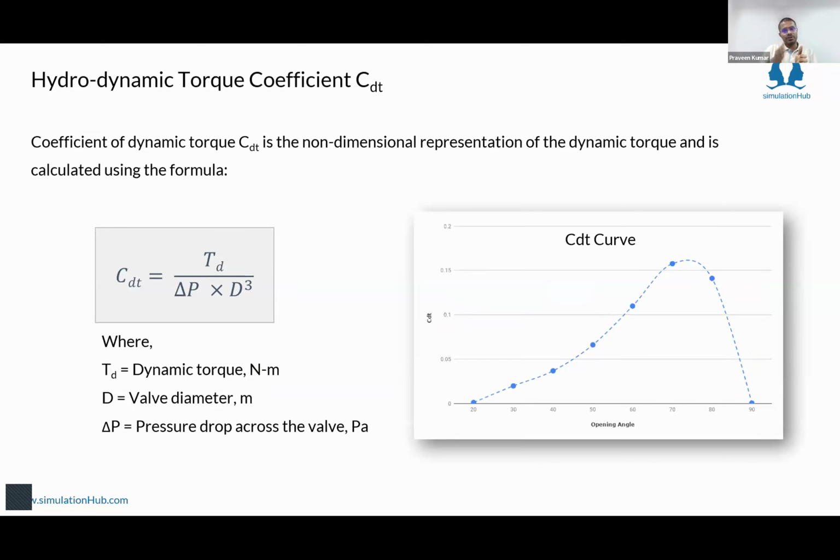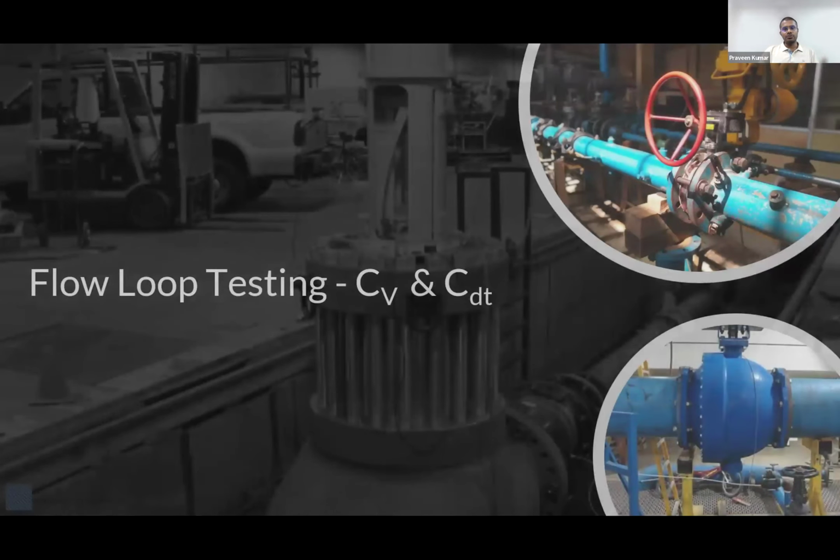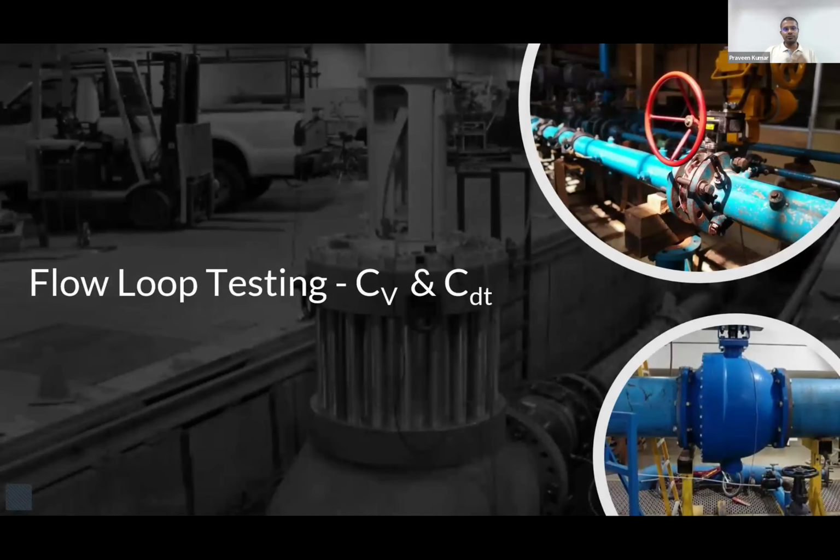Similarly, it is calculated for the complete opening, from fully closed to fully open, and it is represented as a non-dimensional coefficient, CDT. It is calculated from the dynamic torque, the delta P across the valve, and the diameter of the valve. And how they are calculated is in flow loop tests.